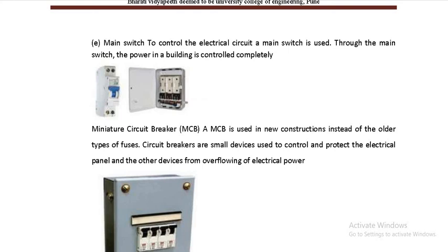And this is the one which we call the MCB. This is normally there in our houses. If there is any kind of fault occurring in any of the devices, this trips. The problem with these fuses is that if the wire melts because of the fault current, you have to get another wire of the same rating, rewire it and then use it. Over here it is just tripped off.